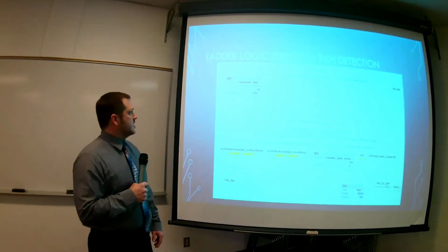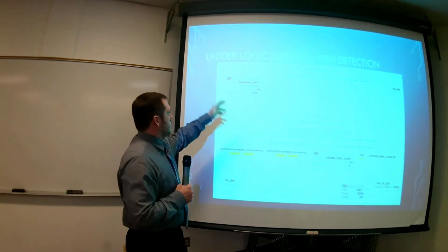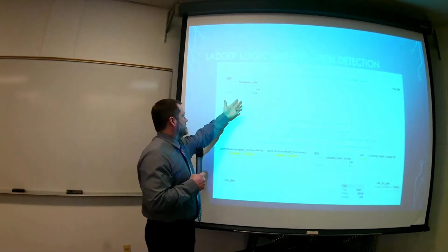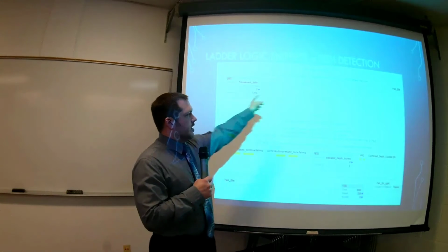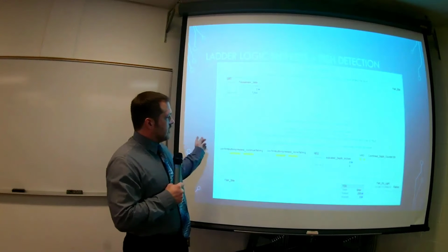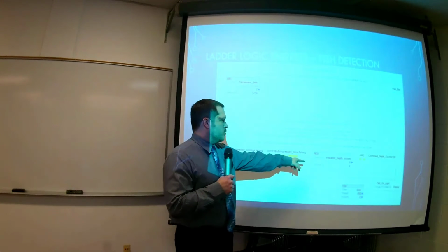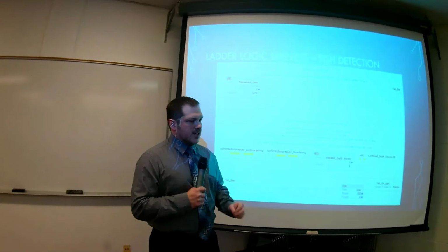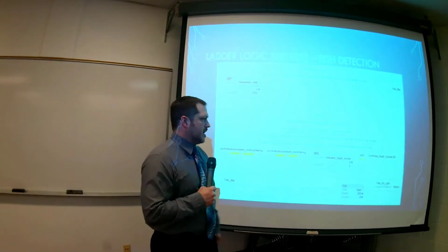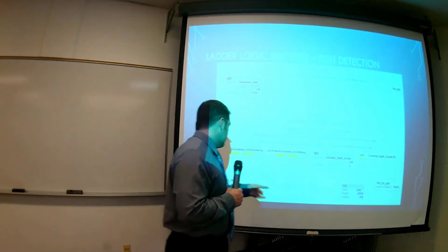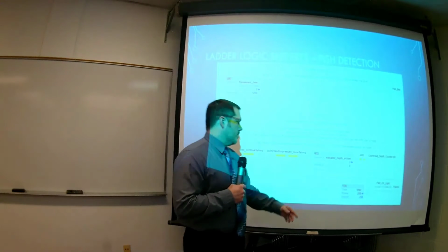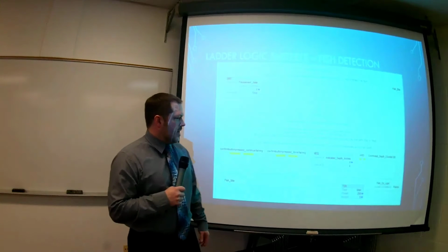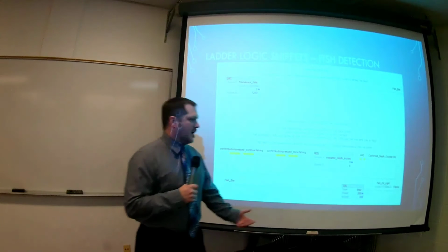Here's a little bit of the logic that we went through. It's shut down, so we're not getting real values in at this point. But as long as we get greater than the value that we had set, which was 72.50, we're going to get our fish bite in. And then as long as we're not equal to 0, which is the 0 set point, and you're not automatically reeling out, so you're not going to energize the motor twice to reel out and reel in at the same time, and your confirmed depth counter is done, then you're going to have your fish bite, which is going to let you reel in. We add a little timer in there just to help prevent spurious values coming in from the flex sensor. And it'll also energize a fish on light and start reeling up.